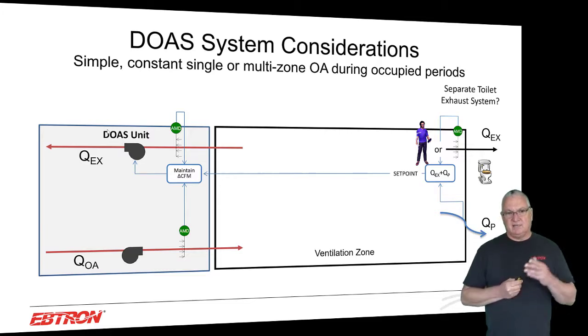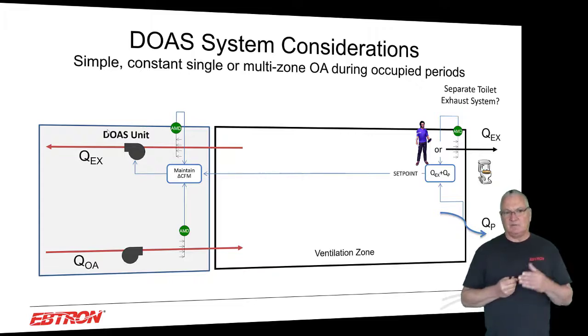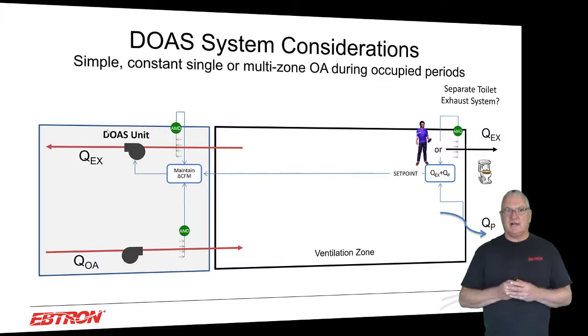And the reasons that you need to do it are just what we talked about previously. It could be wind pressure you're dealing with, it could be stack pressure you're dealing with. We talked about filter loading as a problem. Filter load's different on the intake and the exhaust side. And you're trying to recoup so much outdoor air that you don't have the pressurization air that you used to have.